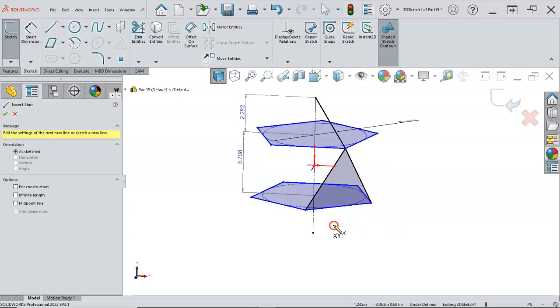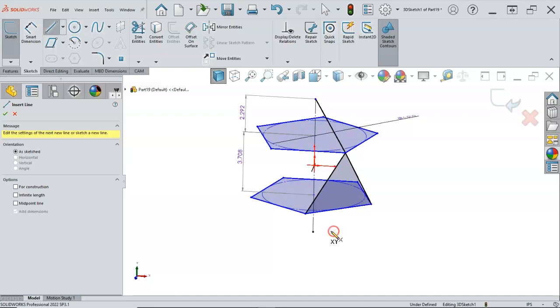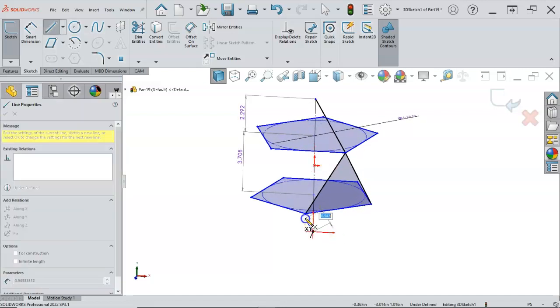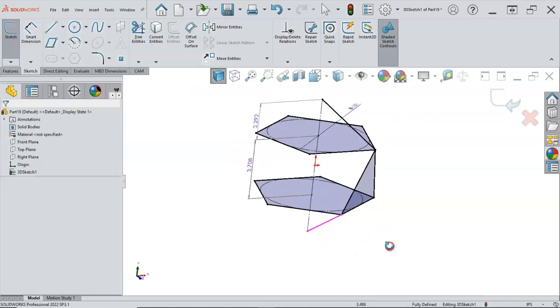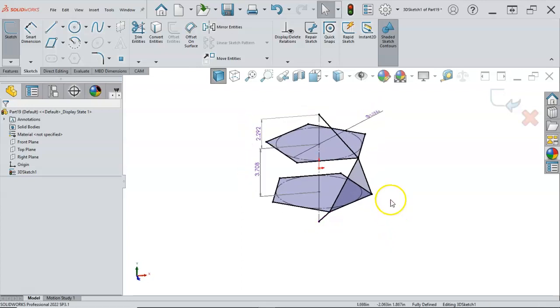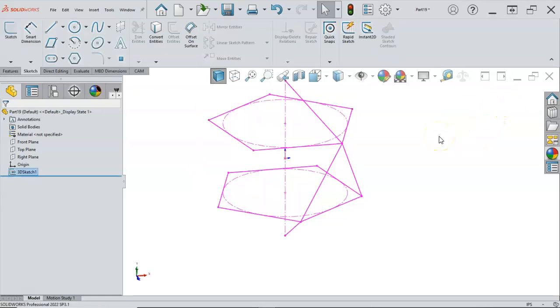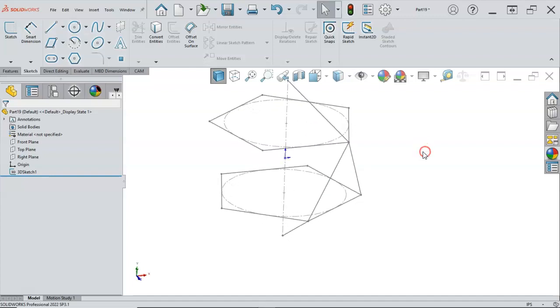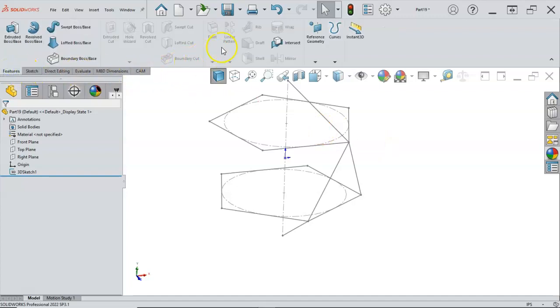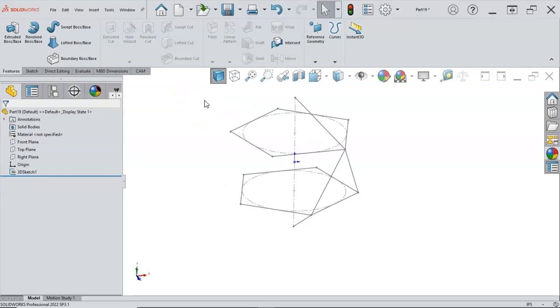All right, so with the 3D sketch too, once I'm out of those planes, I really can ignore the X and the Y, or the Y and the Z, and the Z and the X, as long as I'm going from endpoint to endpoint. So for whatever reason, now it's happy again. So we're going to go with that. All right, so I'm going to use the revolve, or a feature circular pattern, and we're going to generate surfaces for this geometry.